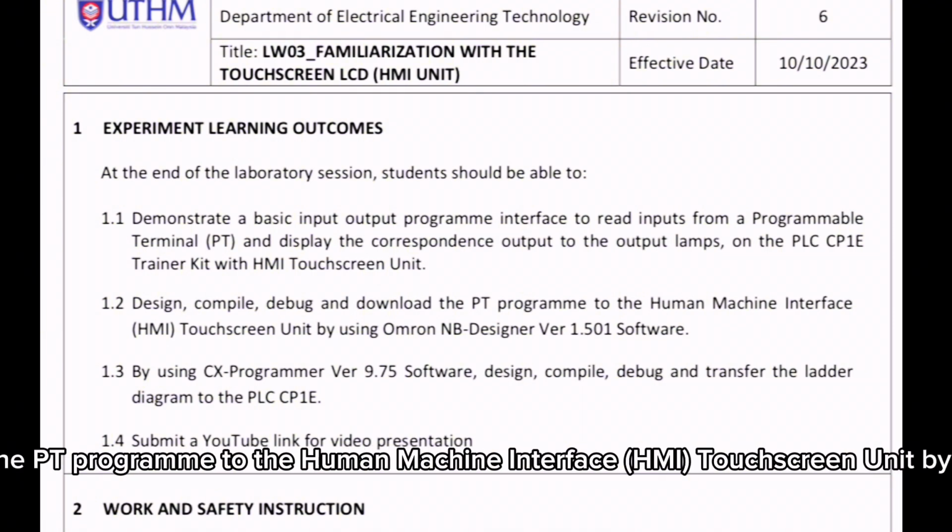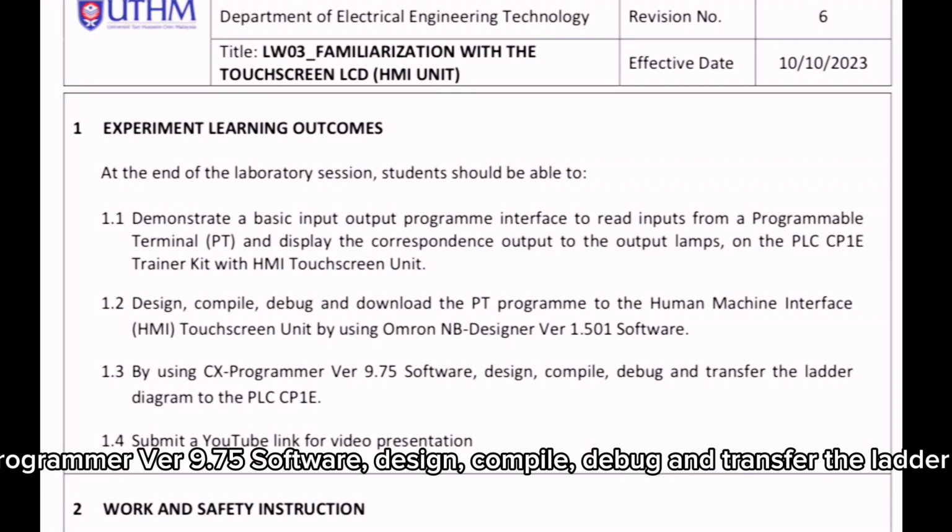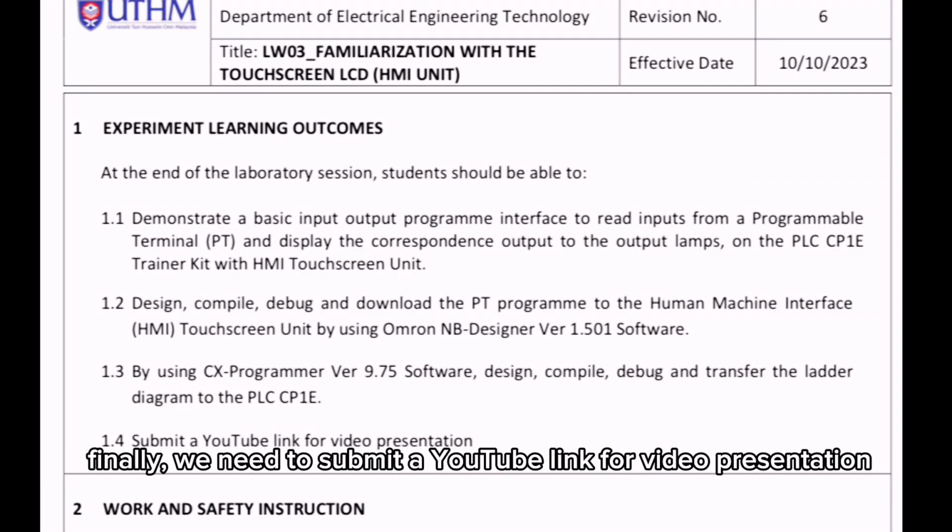Next, design, compile, debug, and download the PT program to the human-machine interface HMI touchscreen unit by using Omron NB Designer v1.501 software. After that, by using CX Programmer v9.75 software, design, compile, debug, and transfer the ladder diagram to the PLC CP1E. Finally, we need to submit a YouTube link for video presentation.